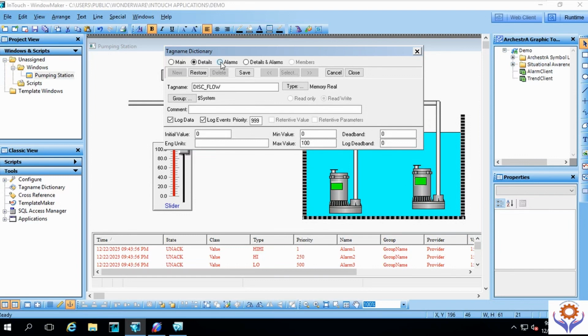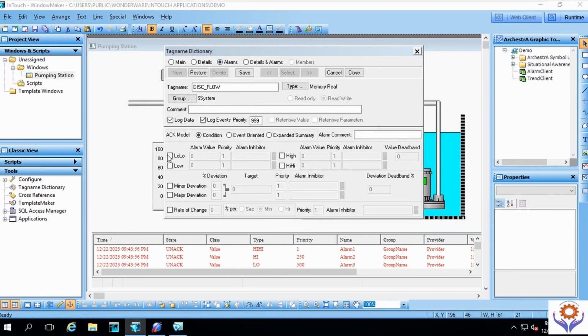Okay, here you need to give when it should give you low, for example. You have to give the value, alarm value. Okay, low, high. See, I will give only low, high. When it will be low, for example, if it is going less than 1, it will give you low. If it goes above 9 meter, it will give you a high alarm.